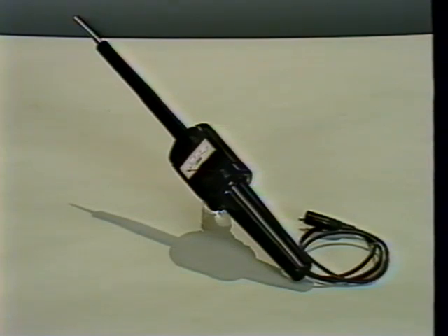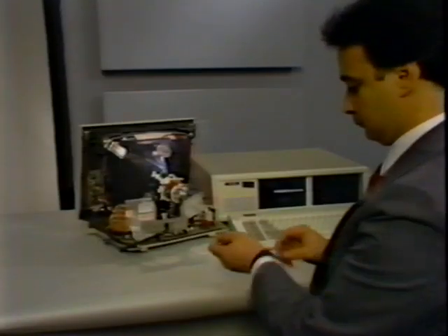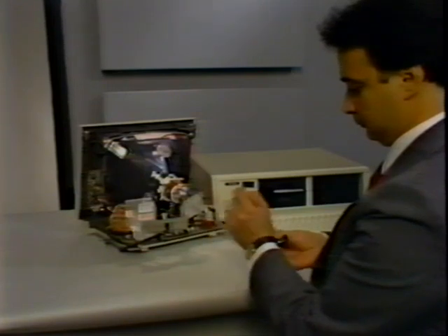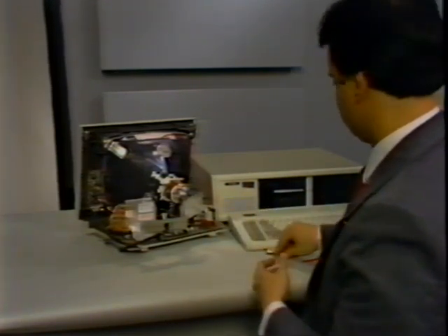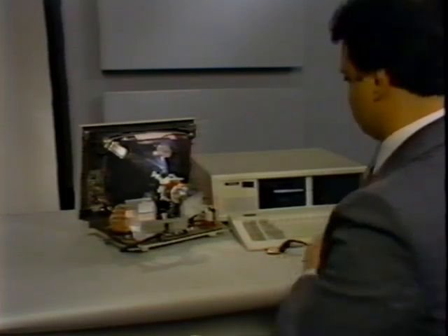There is one voltage measurement that we do not perform with a voltmeter. When checking the anode voltage on a CRT, we use a high-voltage probe. This device is designed to measure the 10 to 40 kilovolts on a tube's anode. To reduce the possibility of shock due to accidental contact, remove watches and jewelry. Do not wear a static bracelet since it provides a current path to ground.